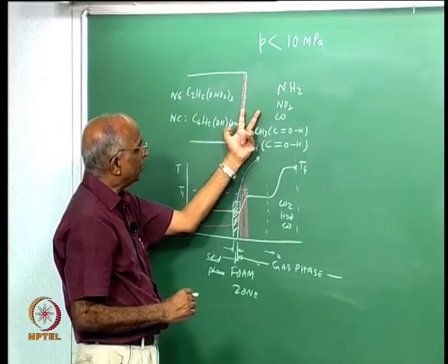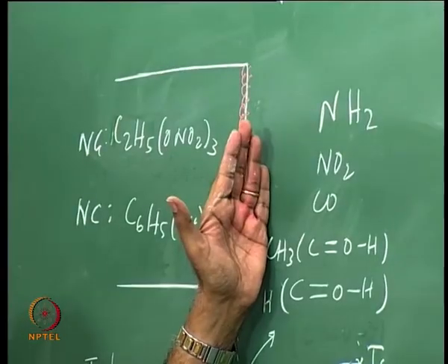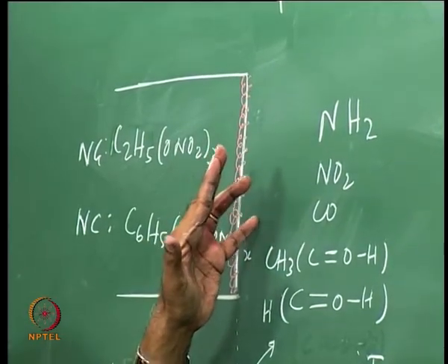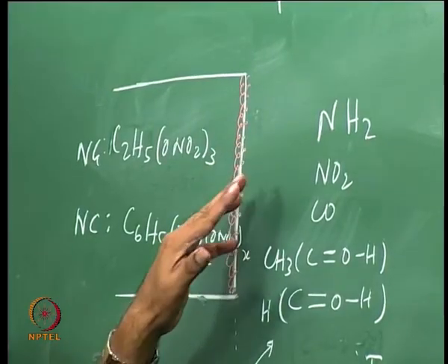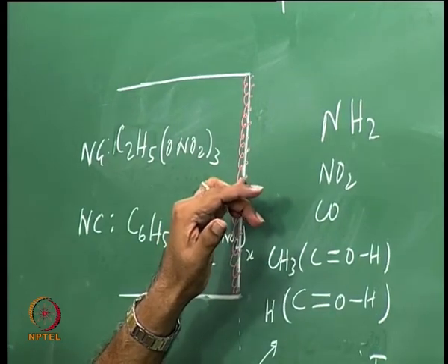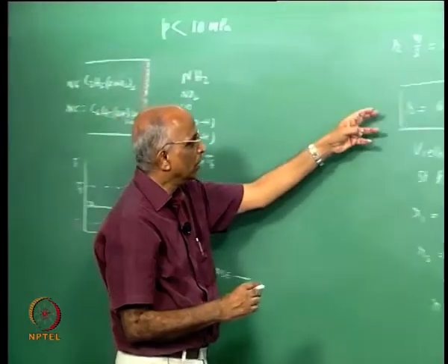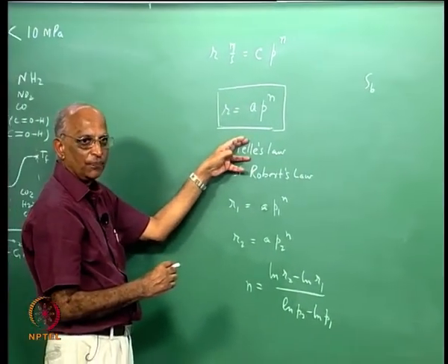We wrote an equation and we were able to say that the velocity of the gases in this zone depends on pressure, and the initial temperature Ti, maybe T1, maybe the surface temperature, activation energy and all that. And since the velocity of gases is directly proportional to the burn rate R of the propellant, we said that the law is R = aP^n, which is known as Saint-Robert's law or Vieille's law.